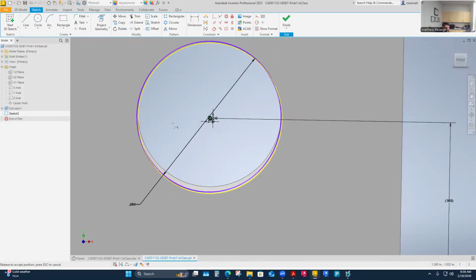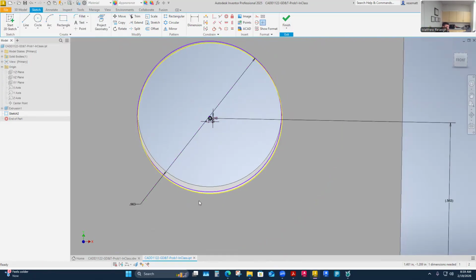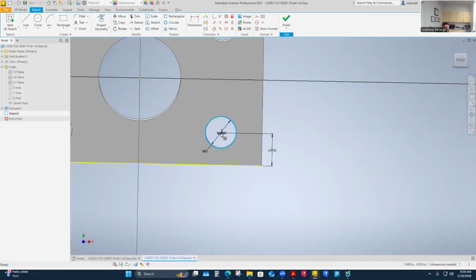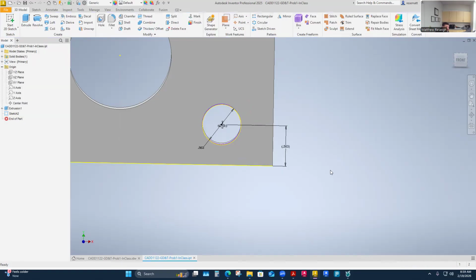If I change from plus and minus tolerancing to this, I get a lot more hole location variation, which might seem to you guys like it would be an inaccurate part. It still is an acceptable part. So it's really interesting to me to see how much variation you actually pick up. That's all I did, that brief little sketch. I'm picking it up in both directions because I'm currently dimensioned in an XY coordinate dimension. So all I want to do is show that, and now we're going to apply that to our drawing to take advantage of that opportunity that exists in GD&T.